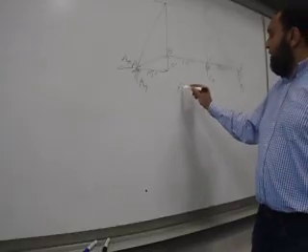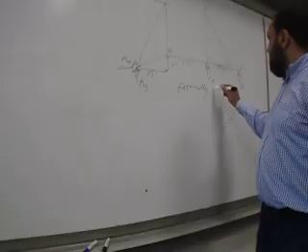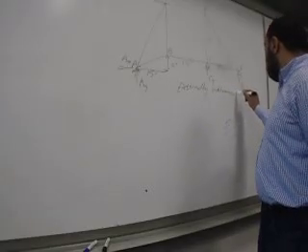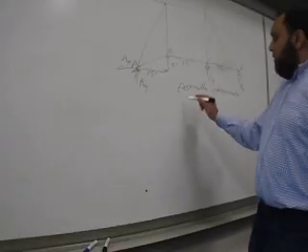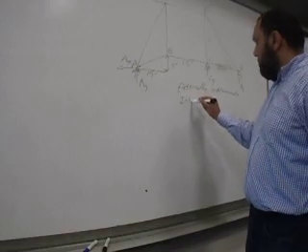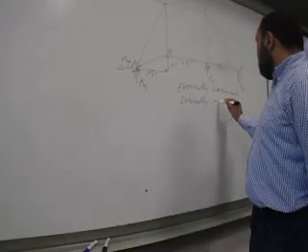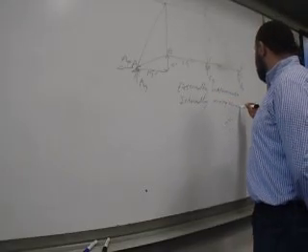What's happening here is that this is externally indeterminate. You're having an additional reaction. However, internally, it's unstable, or it's missing one member.